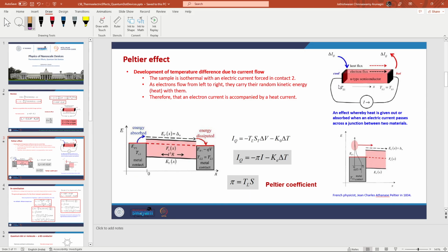which charge carriers are flowing, because for any charge carrier that we are considering, even if we are looking at the holes, we will actually look at holes jumping in this way or that way. So when we are looking at the motion of charge carriers, the heating and cooling effect will be the same. So unlike the Seebeck effect, which depended on the material characteristics, the Peltier effect is essentially only dependent on the direction of the current. So this is kind of a generalization of the Joule heating effect.